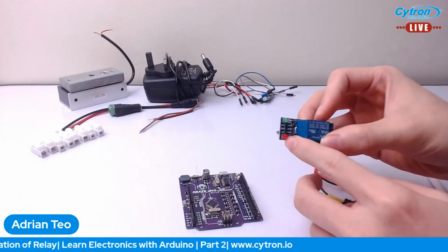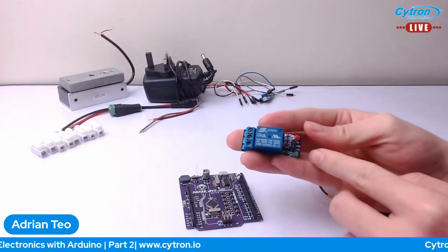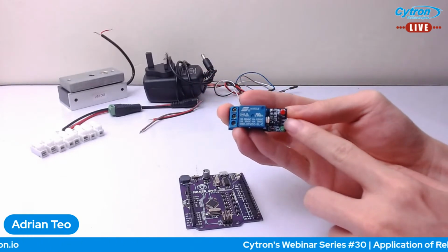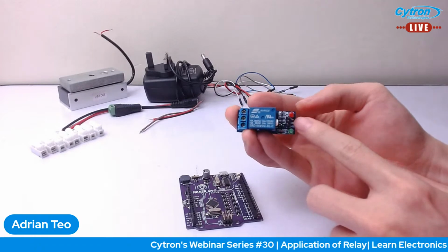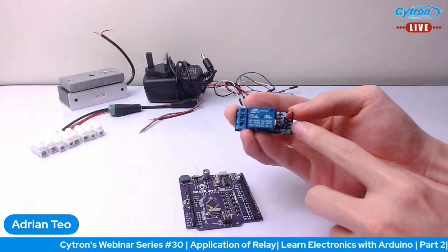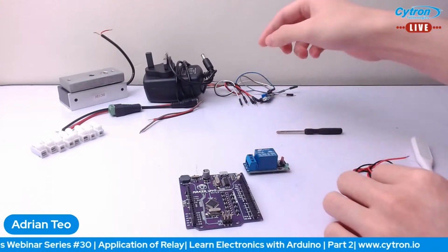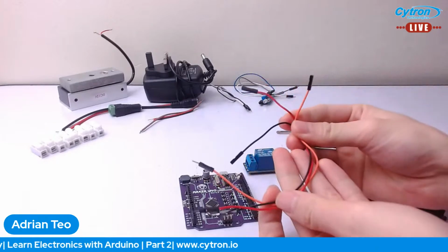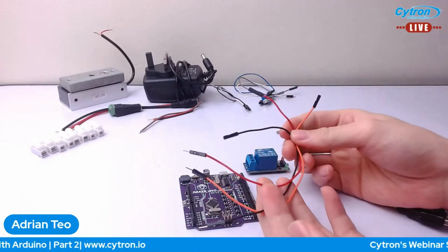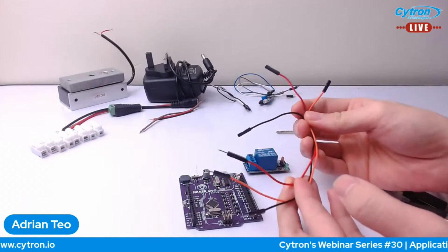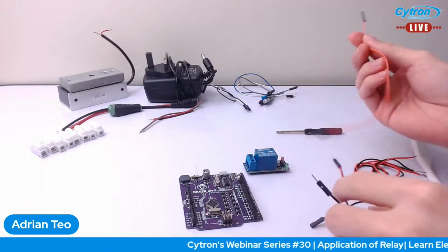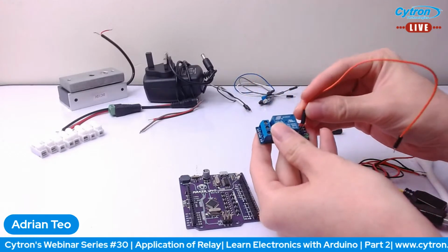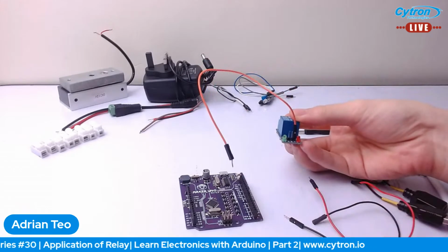All right, next. Over here we have 3 pins on the other end. These 3 pins, I'm gonna read it out. The bottom one is VCC, the center is GND, the ground, and then the top is IN. Following my circuit just now, I'm going to go ahead and connect these 3 wires using a female to male wire. Bear in mind that I've checked all these connections already to make sure I don't make the same mistake as last week. Last week, one of the wires was disconnected internally. So first, I'm going to connect the IN like that.